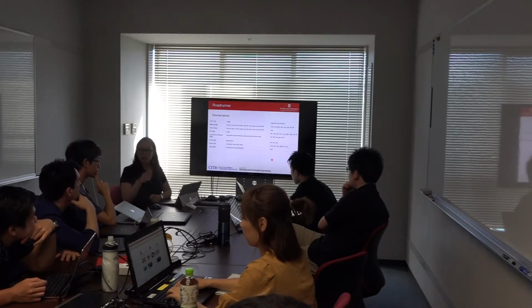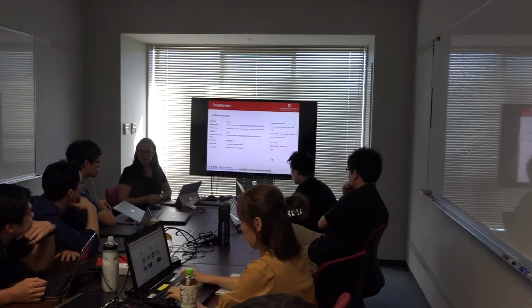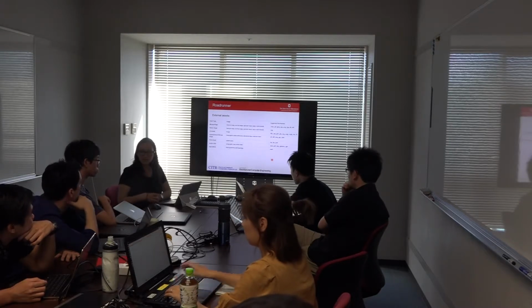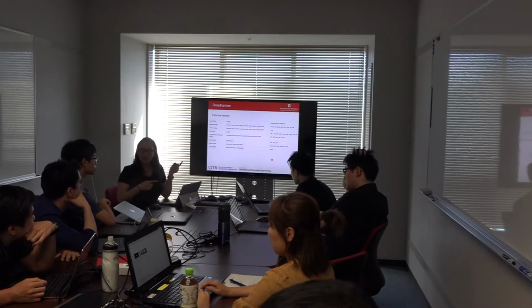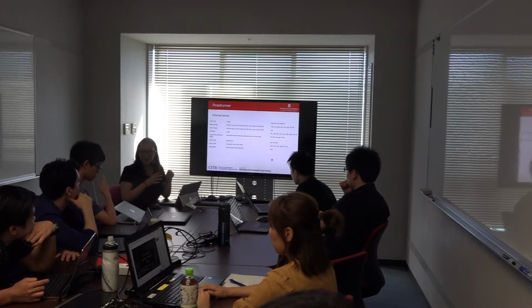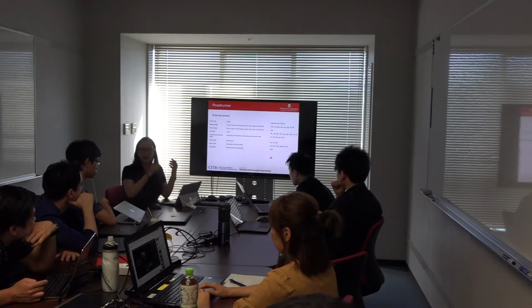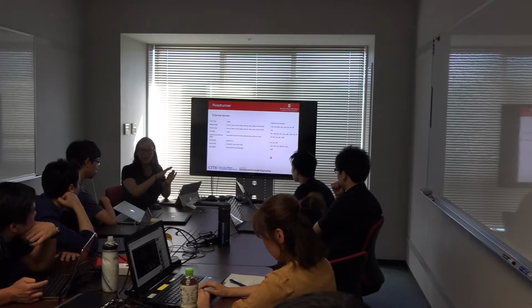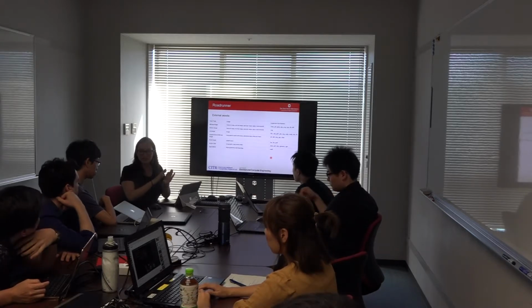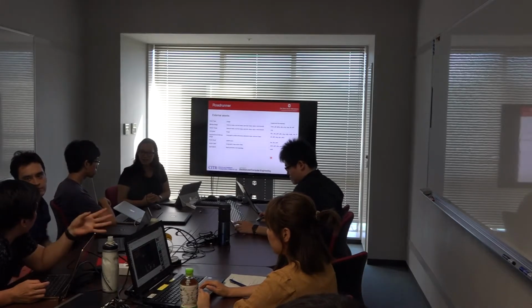I had to set it by hand. Yeah, so did you try to eyeball it to overlay over the OSM? The thing is that it doesn't work because the center of the OSM file has different numbers. And it doesn't allow me to do that. The PCD files are a number of them, so I manually added a transformation. But when I wanted to import it into the same window, it said that they had different origin references. It complains, it wouldn't add it if it's not close to the origin.